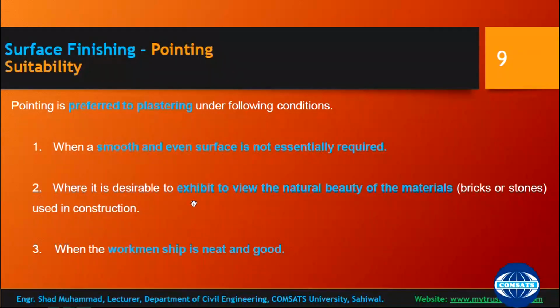It means if you want your structure to look natural, and you don't want to make it something artificial, then to exhibit or maintain the natural beauty of the material, bricks or stones, you can prefer pointing rather than plastering. When the workmanship is neat and good, okay, that is also necessary, because pointing is a slow process and needs a lot of skilled workmanship.